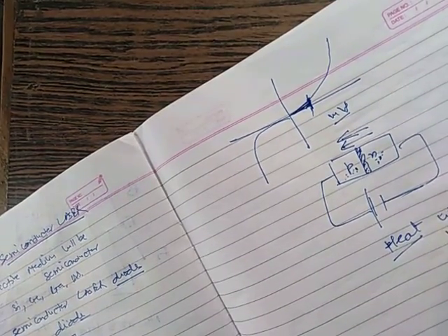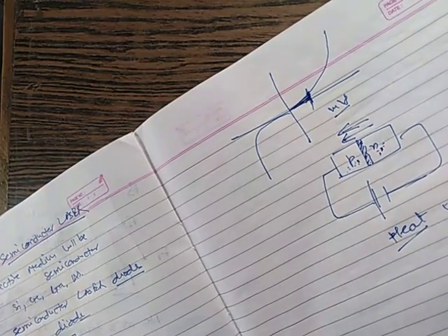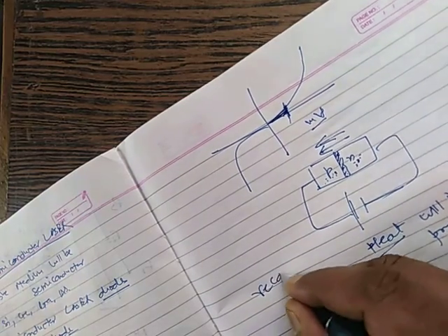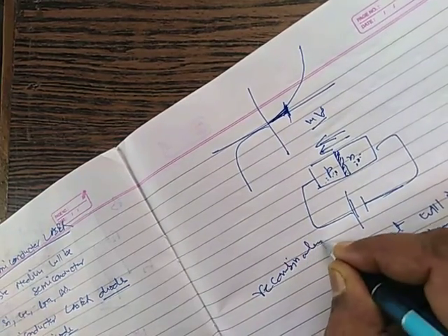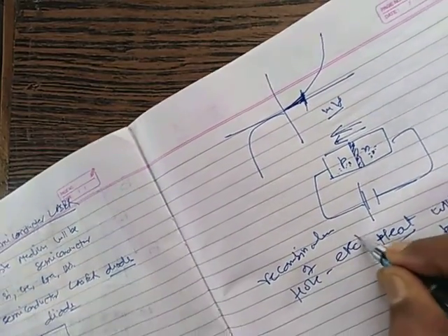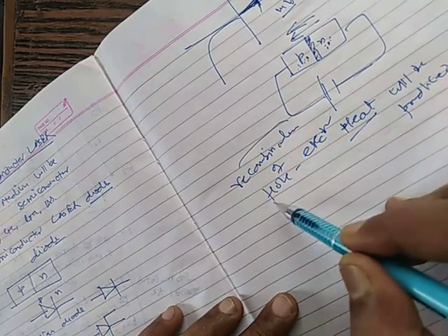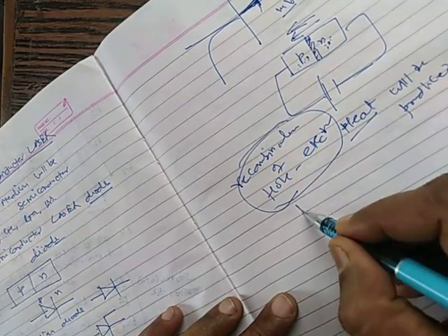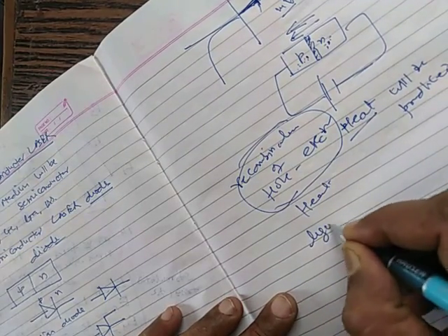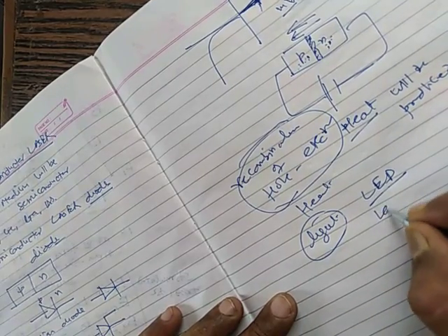That's why we say that when semiconductors are working, heat is produced, and this heat is basically due to the recombination of holes and electrons. Now, if somehow this recombination of holes and electrons, instead of converting into heat as in a normal diode, is converted into light, then it works as an LED or the laser diode.